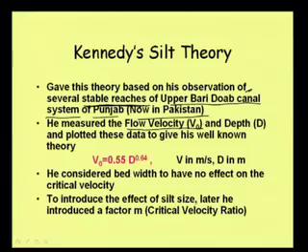So, this V0 he measured, and of course, he considered that this V0 velocity will have a relationship with the depth of flow. That means, if we observe the flow velocity and depth, then we find that the channel remains stable for a velocity, and at that velocity the depth has a particular value.